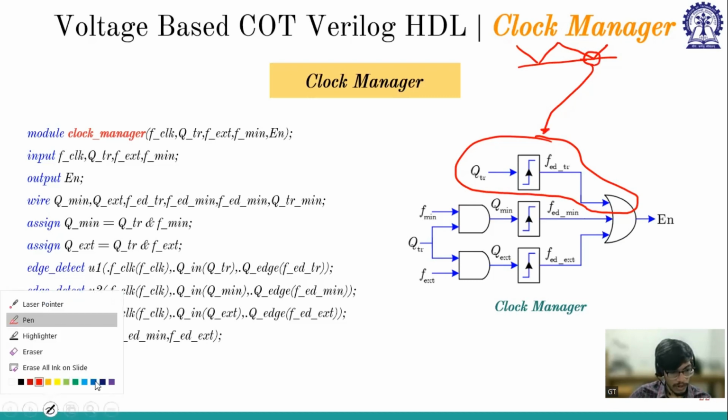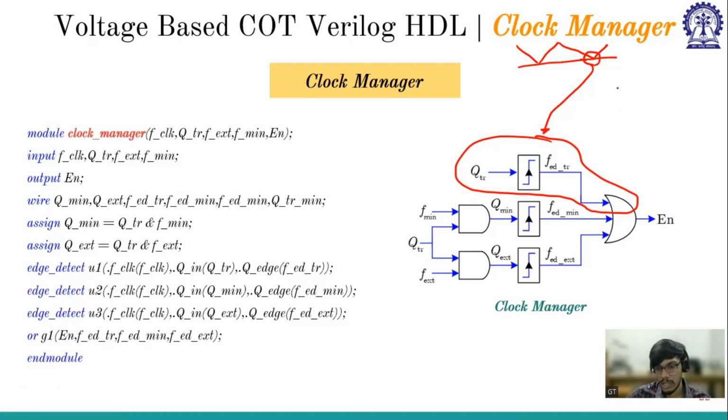So what if there is some scenario, say this is my V reference, and after turning on, this is my V naught. Now here my constant on time ends. So what happened? There should be this minimum off time, and then it has to turn on again so that it will cross, right?